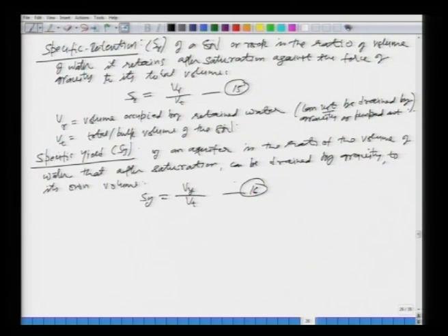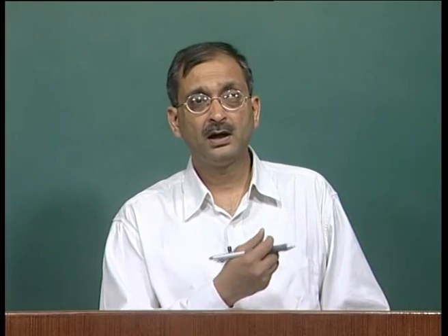Let me number this equation as 16, where V y is the volume of water drained or pumped out. So, this specific yield gives us an idea about how much water is actually available. There is a total pore space, or the porosity. Out of this, if it is saturated, a certain fraction cannot be available for any useful purposes. That is your specific retention, and the specific yield is something which can be pumped out or we can use.